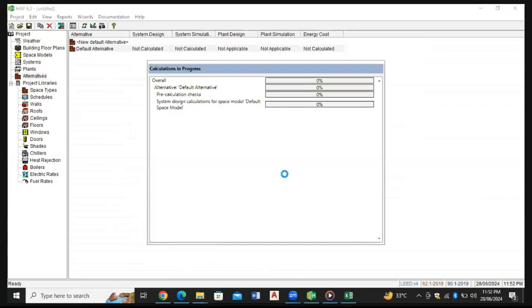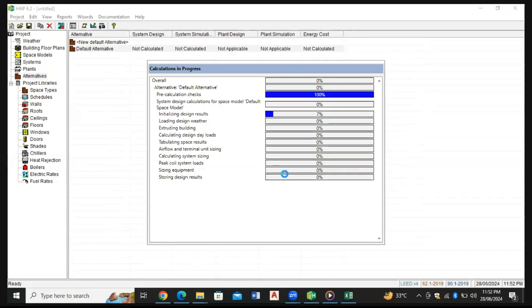It will take time, as I didn't mention it earlier, but it's a heat balance method. In the heat balance method, we use very few pre-calculated factors, and it is the most accurate method. But it is a complicated method, which is why it takes a lot of time to calculate all those things and generate a report.